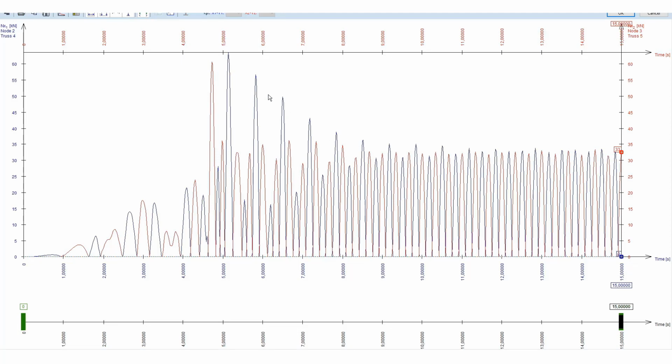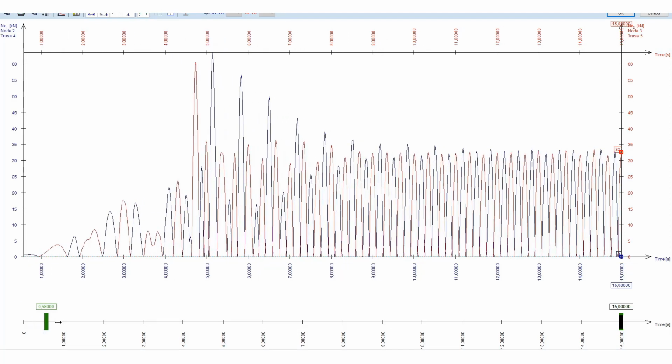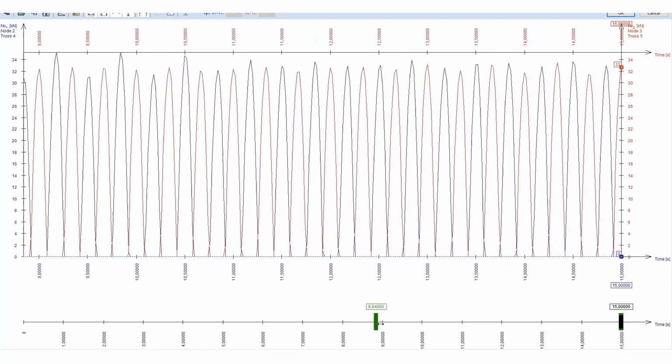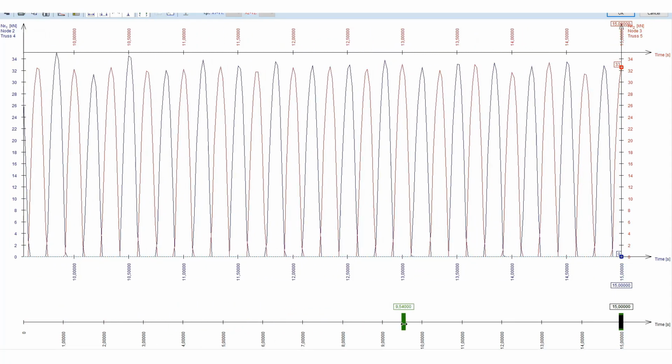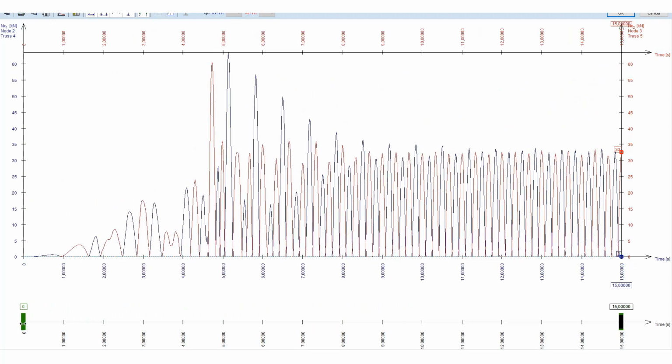Even if we have only one active brace in one direction, the force is not doubled. The reason is that in the case of a nonlinear system, the stiffness changes during the vibration, and this stiffness change has an effect on the response. In our case, the smaller stiffness brings the natural frequency even further away from the excitation frequency, leading to smaller global responses, which on the other hand is distributed just on one activated brace.